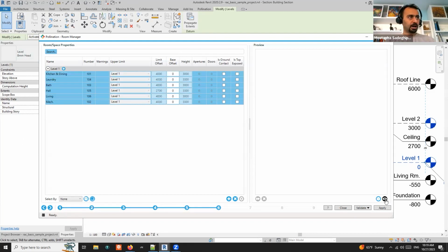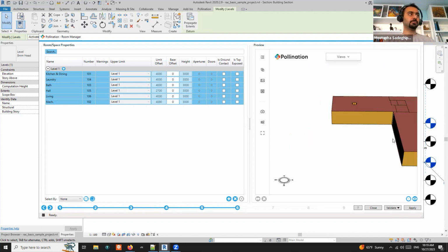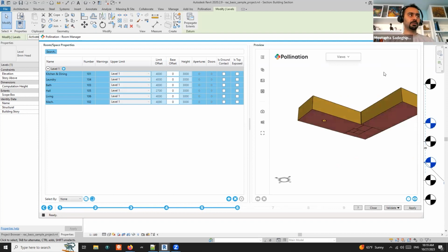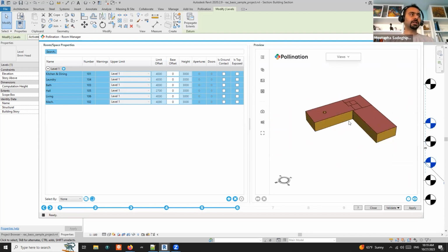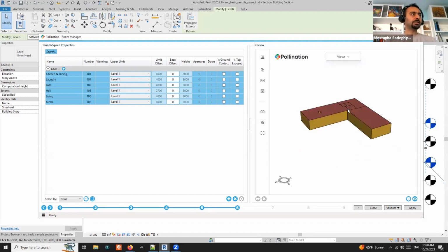And then you press on this icon to reload preview. What it does is it basically takes all these models that are parsed, and then it generates the analytical model under the hood and tries to render it. Why is it important? Because you want to see all the issues in your model before you send it to simulation. Basically, the approach is things are going to go wrong, so let me help you see it before it becomes a problem later. So now we see everything extruded, 3000.